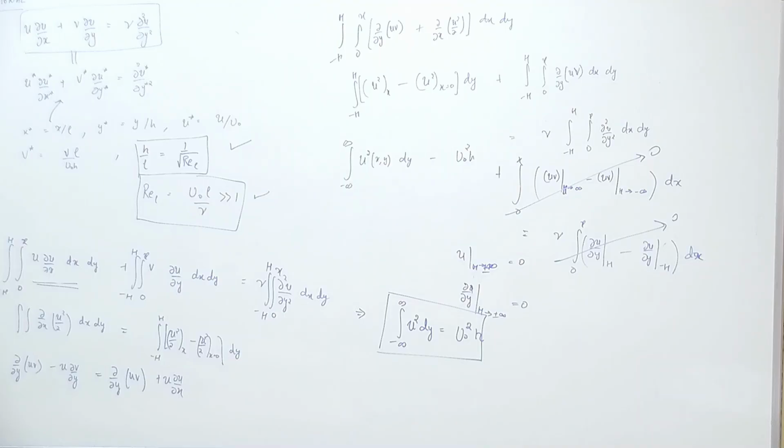Okay. So, in a jet flow, your mass flux, or volume flux if you just ignore the density, is not constant in x, because you have a continuous entrainment of the fluid from the sides that is moving along with the jet.